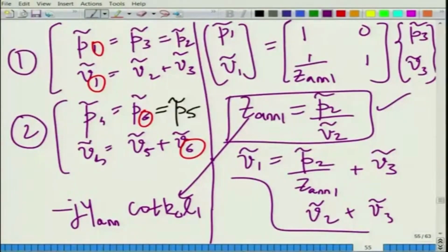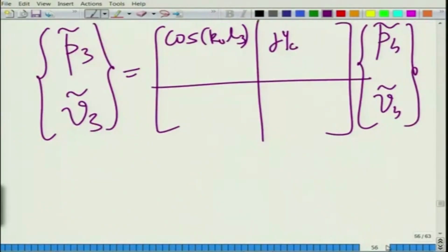If they are not equal to L by 2 and L by 4 respectively, then the extended inlet and outlet chamber is not tuned. If you have just a tuning of the inlet and not of the outlet, it is called a singly tuned muffler, or single tuned muffler. We can appreciate all this when we do some parametric studies shortly, but before that let us quickly